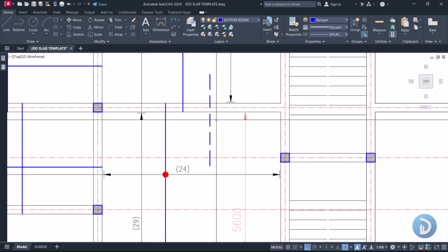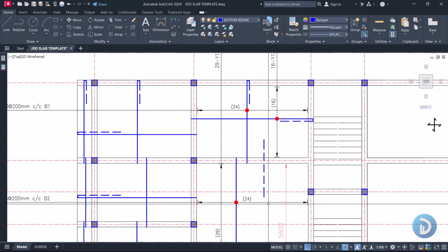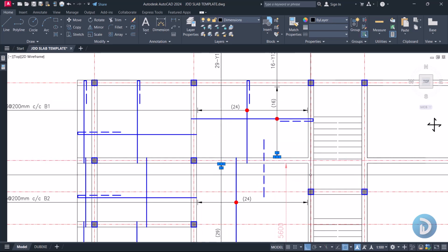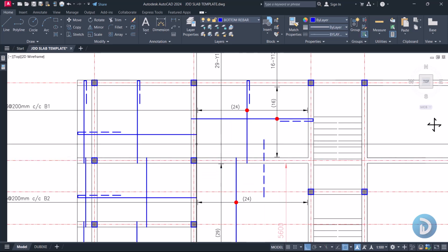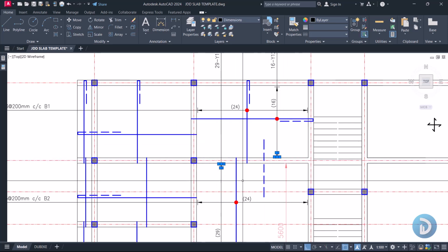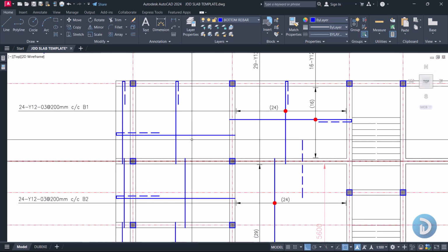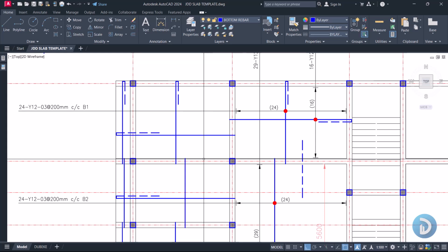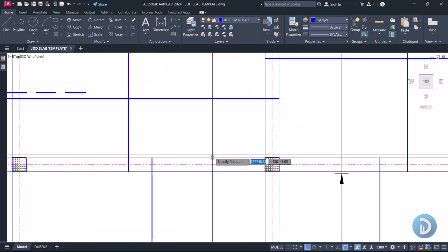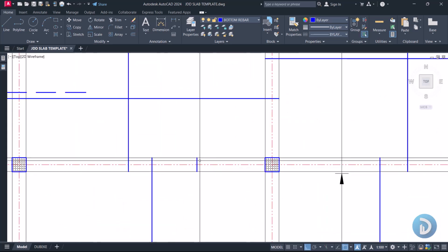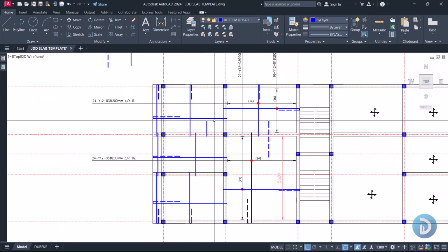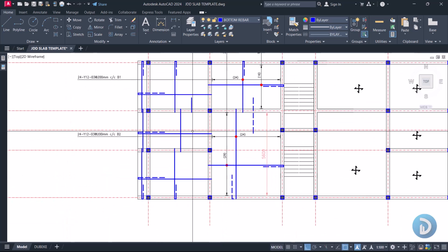Okay, now this is allowed to run on this very beam from this point to this point. So this top reinforcement is only functional within this span. On getting to this part, we have a different grid, or a different beam structural arrangement. So for this case, we'll have our top bar here, which will also go 750, because here we have 3 meter as our clear span.